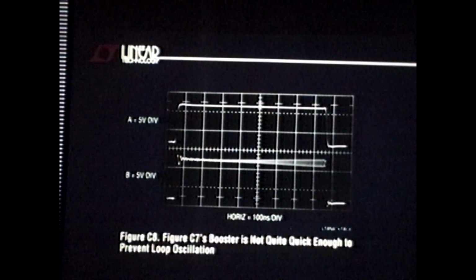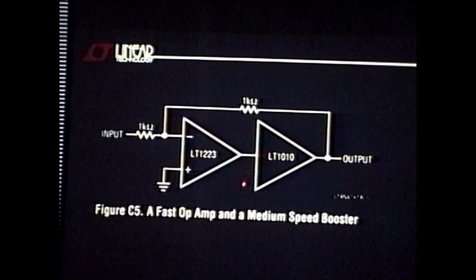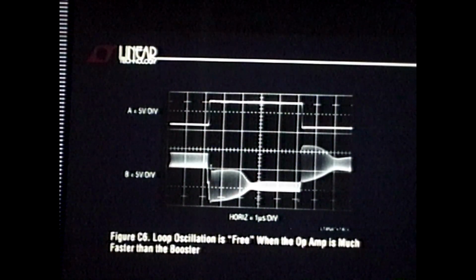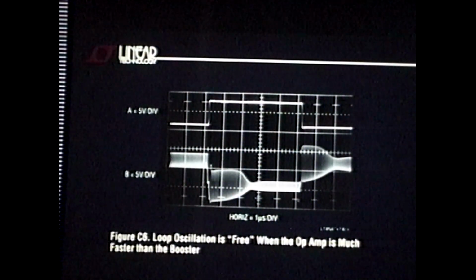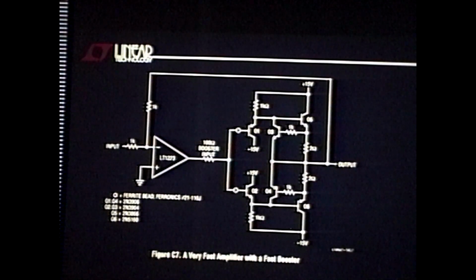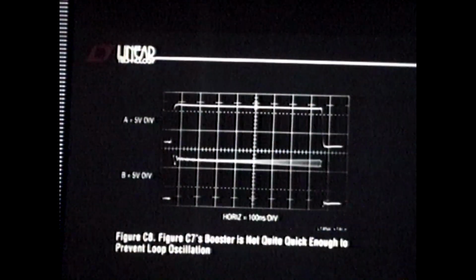You still got too much phase, but you notice something? That's a 20 megahertz integrated buffer. Look at the frequency of oscillation. Maybe 10, 12 megahertz, if that. This is a discrete buffer. It's faster, take it from me, significantly faster, but not fast enough.